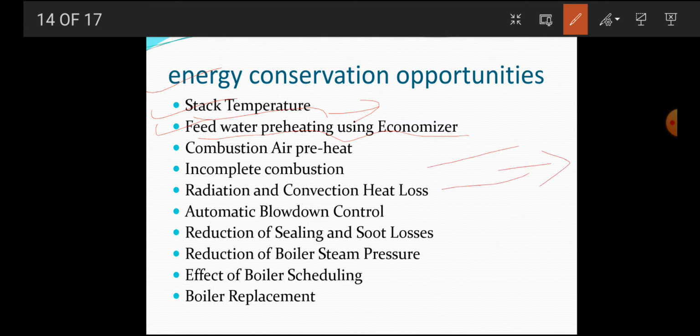The flue gas exit temperature from the boiler is usually maintained at 200 degrees Celsius, so the sulfur dioxide in the flue gases does not condense and cause corrosion on the heat transfer surfaces. For a modern 3 pass shell boiler firing natural gas with flue gas exit at 140 degrees Celsius, a condensing economizer would reduce the exit temperature to 65 degrees Celsius, increasing the thermal efficiency by 5%.